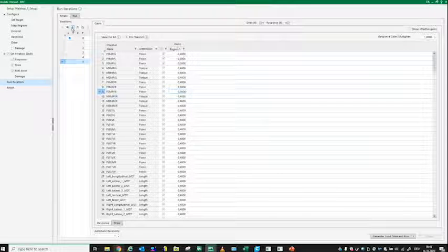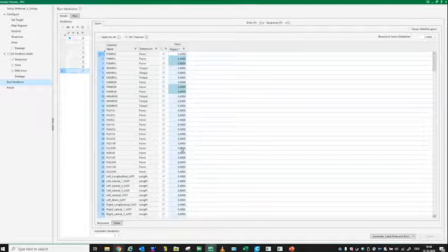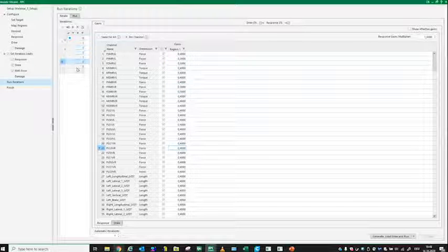So I go here and use that one for several iteration steps. And then in the end, I will say, okay, I now need to have everything on 0.4 for this region here, and then I'm fine with that. So this is some kind of scheduled iterations I can set in advance. So you see that RPC saves all the gain settings I just made. And if I hit the generate load drive and run button, it will go through all these steps and just use the gains I have here.